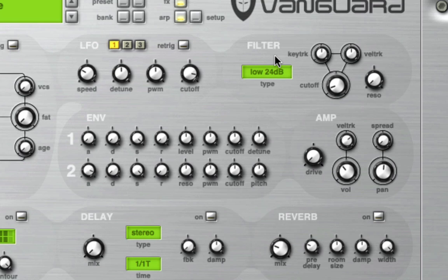it's almost as if the oscillator continues in the background, and every time you hit a key, you hear wherever that waveform got to in its oscillation. It's essentially a sine wave, this low frequency oscillator. Some other synths give you options of using square waves, sawtooth, so you can actually get different sounds. This one is a straight up and down sine wave. So what you're doing is you're kind of picking that sine wave up at somewhere along its wavelength, and it's different every time. So that's what the re-trigger button will do.